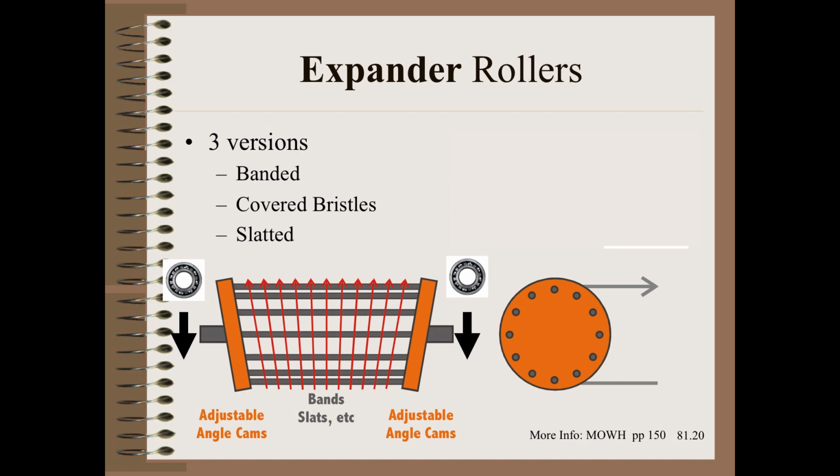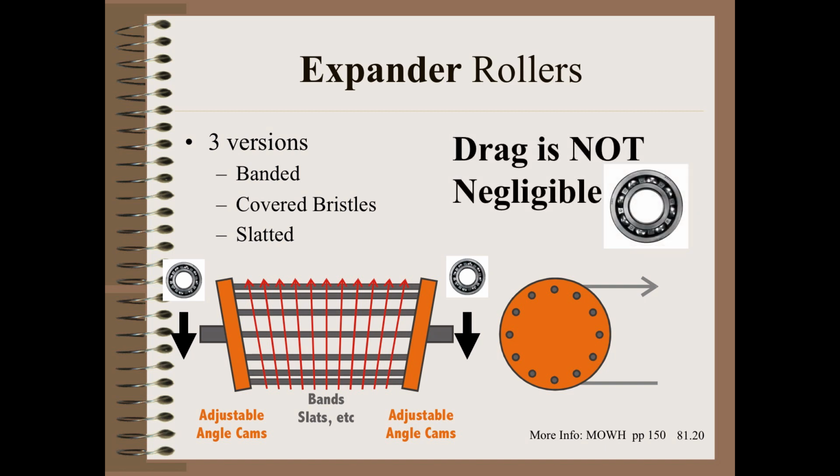As you might already suspect, this roller has a lot of internal drag, and that translates to a large machine direction drag when the web powers this device. This spreader is nearly unique in that it operates well enough where a portion of the center might be in traction while most of the width is in sliding.